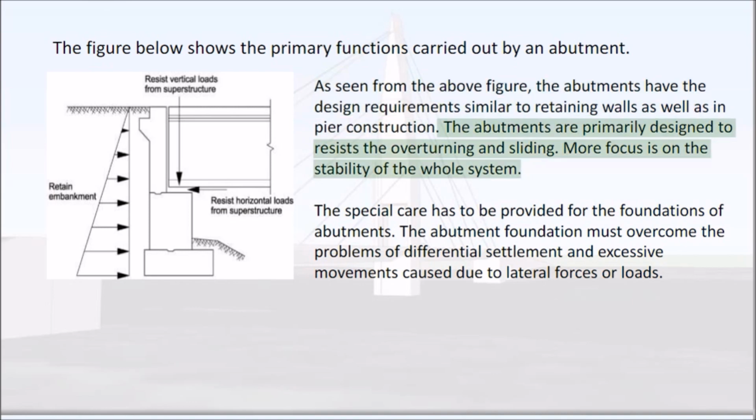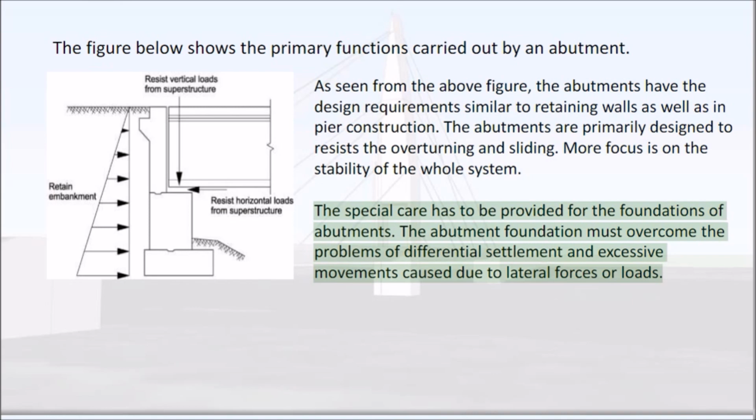The abutments are primarily designed to resist overturning and sliding. More focus is on the stability of the whole system. Special care has to be provided for the foundations of abutments. The abutment foundation must overcome the problems of differential settlement and excessive movements caused due to lateral forces or loads.